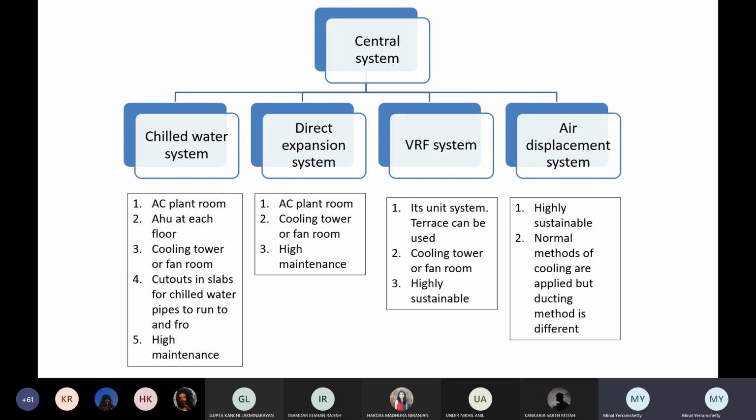Now in chilled water, what we do is we keep the evaporator in water. So the water is the one giving up its heat for the evaporator, for the refrigerant to turn into gas, and then that chilled water is taken up. Versus a direct expansion system, where I put a big drum of air, it's just chilled air. Now mind you, chilled air is not like your air in the AHU; there is no 25% extra fresh air in this. This is completely hermetically sealed kind of, no, it can't be sealed.